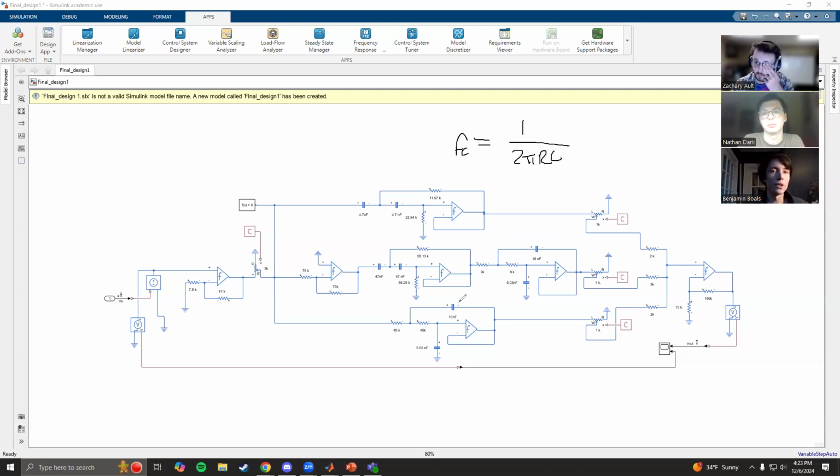So in order to compensate for that, we tried to widen out those cutoff frequencies a little bit to get a flatter response, and we still get a pretty good desired result of being able to control the frequencies we wanted. And then like the high pass, the signal goes out to a potentiometer that lets us control the magnitude of how much signal goes into the summing amplifier.